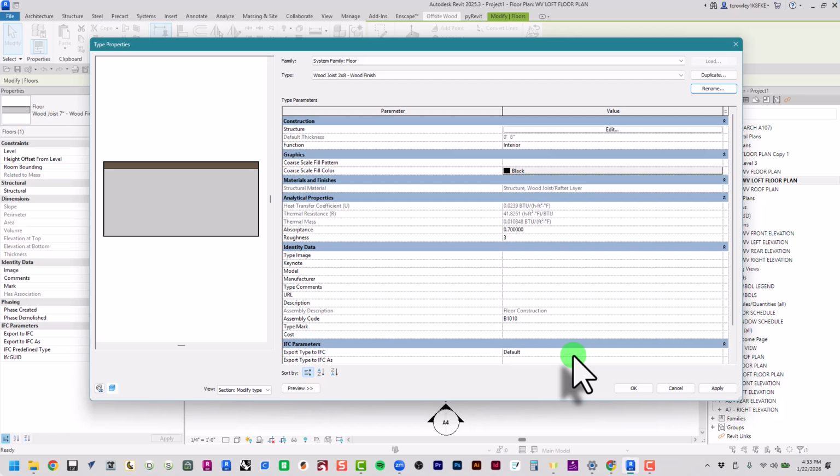So if I were to go out and buy a 2x4 and it was 10 feet long and I had a bunch of them and I started walking on them, because they're so long and are not supported over those 10 feet, they wouldn't be able to support our weight as we walk around. So to help with that, we can either add posts below it, so that they're not cantilevering for 10 feet, but instead maybe they're only floating for 5 feet because we've got posts underneath in the middle.